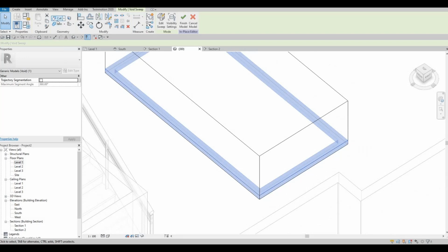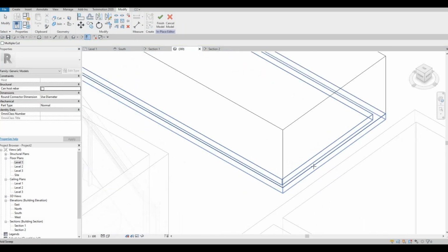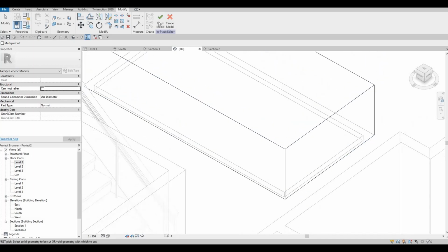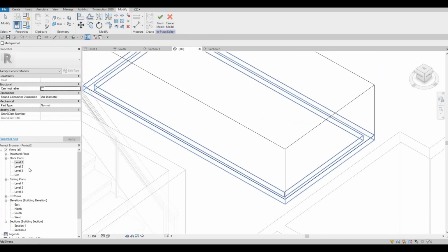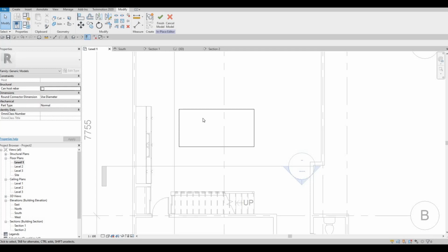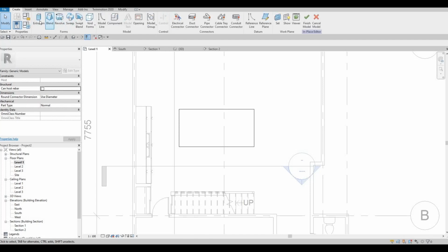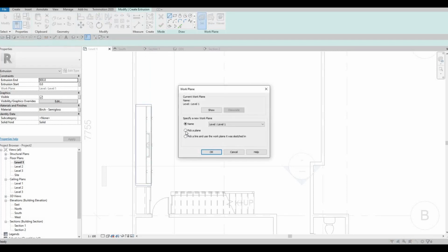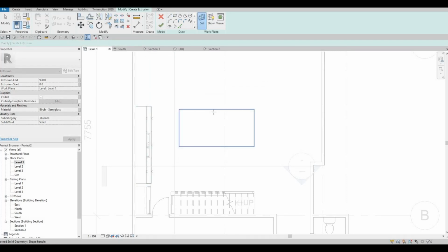And then here you need to cut geometry. Once you do that, as you can see, we have it cut already. And we're not done yet there. We need to create our top. So what will happen is once we create our top, we're gonna extend this backward. So right now, we're gonna create again an extrusion. We're gonna pick a plane, which is the top of this island. And then now it's gonna be 25.